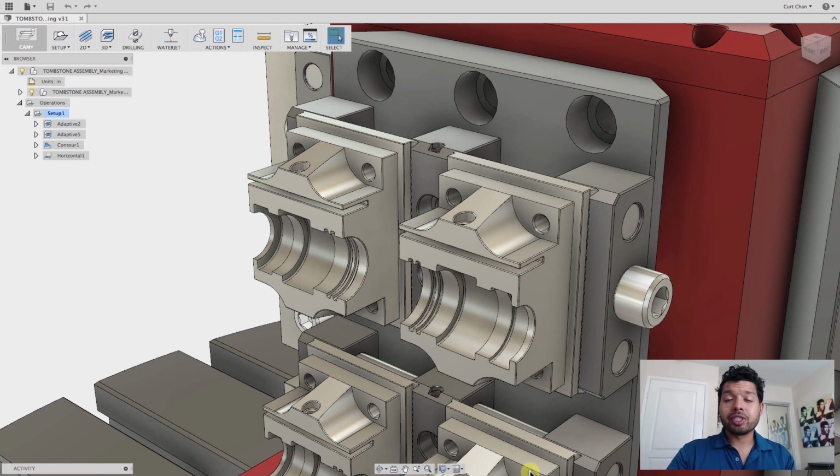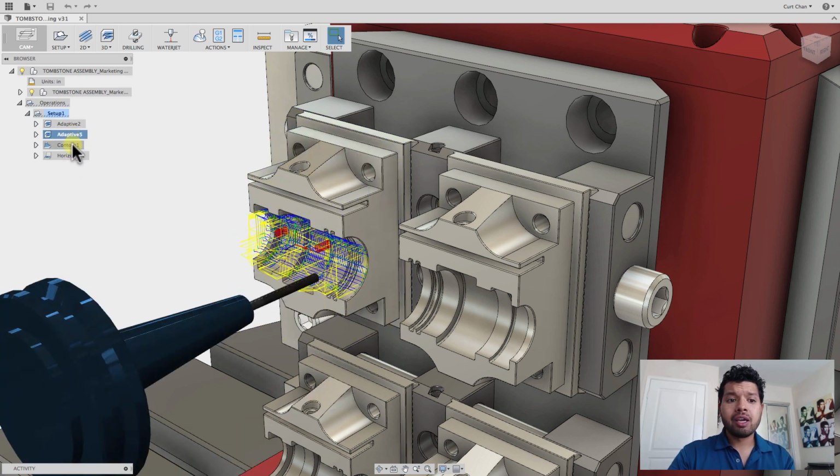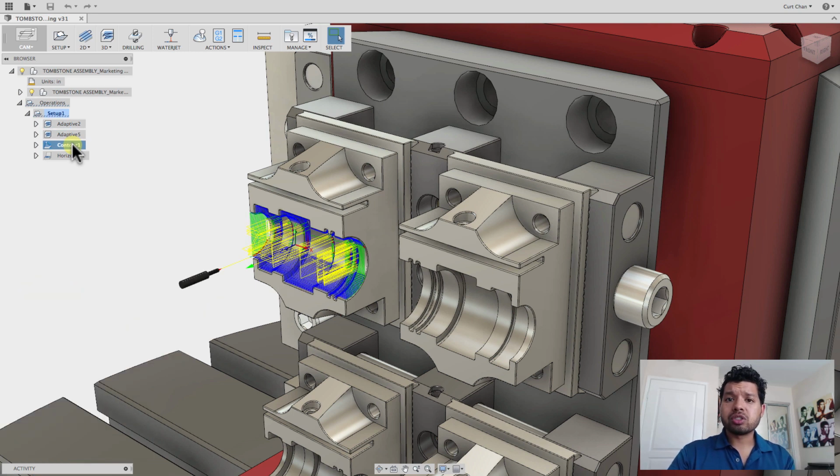But now talking about some other tips, let's talk about 3D strategies. And this is actually really slick. We took this from HSMWorks as well as Inventor HSM, that HSMWorks technology, something called Derived Operation. I've already set up my adaptive, my rest machining adaptive, and I came in with a 3D contour to just take a look at angles of 90 degrees to 45 degrees. Now I want to take all those same parameters I have under the 3D contour and apply it to a parallel strategy. Boundary conditions, tools, feeds and speeds, everything.